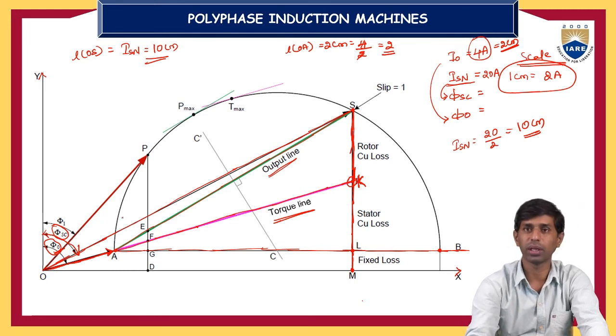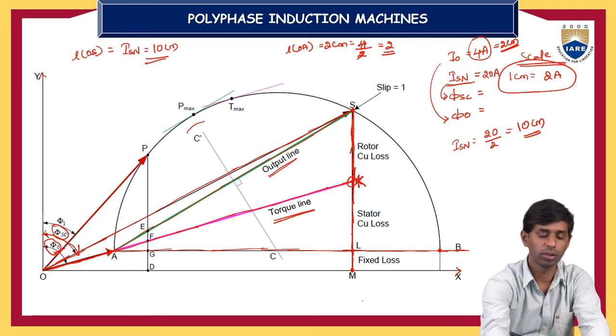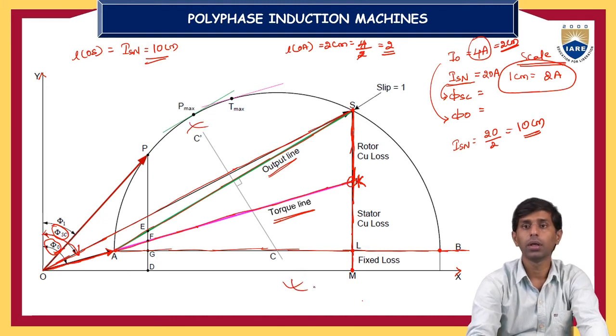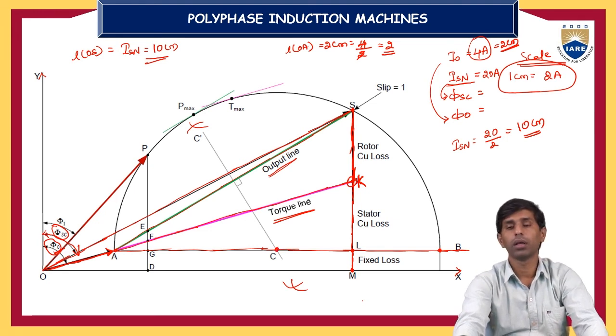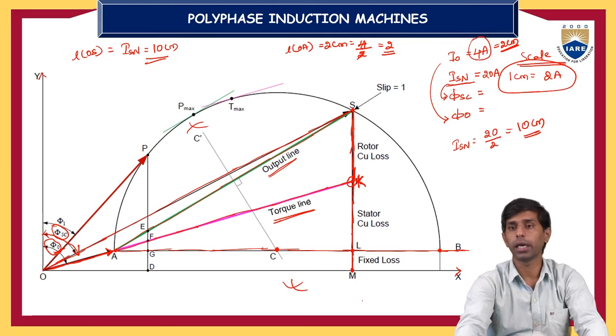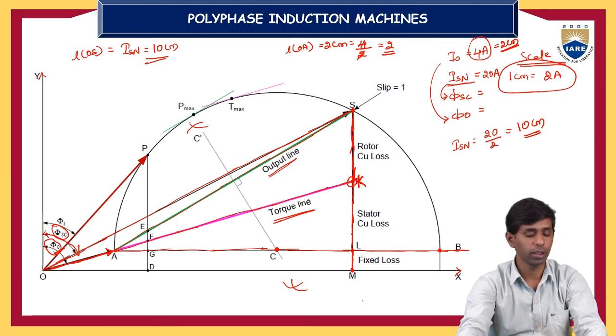So by taking more than half of the radius, you can draw here and here two curves, and here and here two curves that intersect your AB line at a point called C. That acts like a center for the circle.